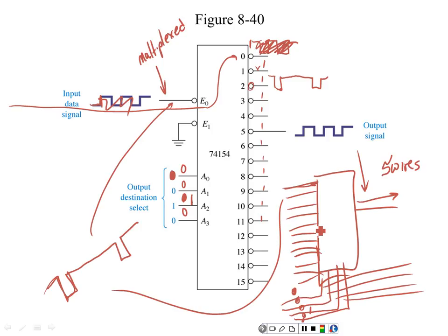And then if you go below that, it wouldn't be worth your time to multiplex. If it takes as many wires to multiplex as it does to send the signals directly, then there's no point. So I could send 4 bits of data, but it would take 3 wires. So now our cost savings are not that much, right? And if I send 2 bits of data, it'd take 2 wires.